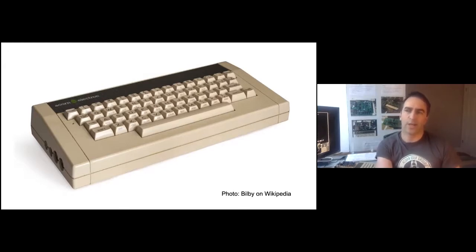I believe the start address of the screen memory is settable, but only at a fairly granular level, something like 32 or 64 bytes. So smooth scrolling doesn't work nearly as well in games. There's no Mode 7. The audio is basically bit-banged. It's basically a GPIO, so you can turn it on and off. It's a square wave that gets filtered a bit at the end.